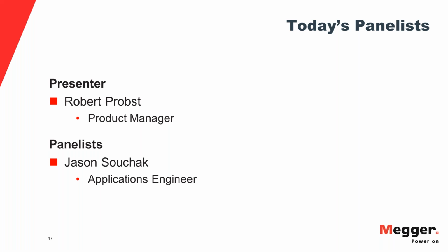So online PD testing to me is nice for an alarm system if it's continuously monitored. If it's the type of thing you do only periodically, once a year or something, I don't really see the value in that. The offline testing is much better for predictive testing.